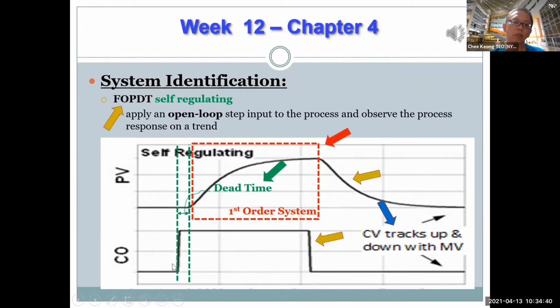Usually you use the step function. By doing this, we have this process variable, which we want to observe whether it responds together. This is basically the process variable, right? And if you look at the step function comes up and goes down, basically the process variable will follow through, right? Go up and then come down again.